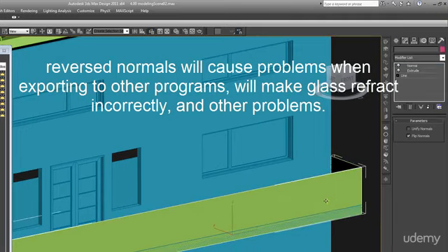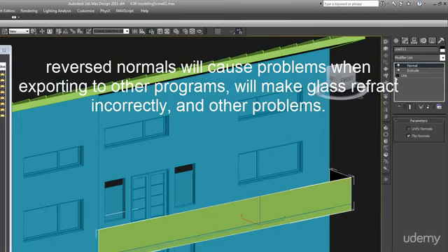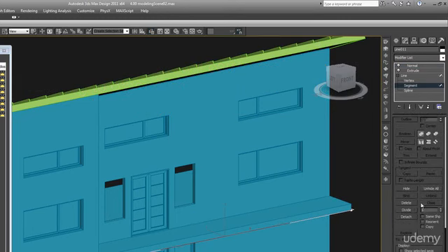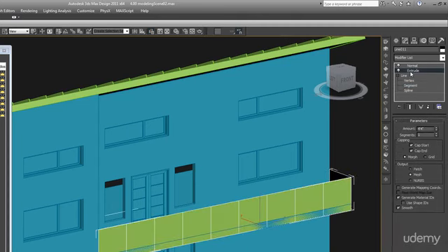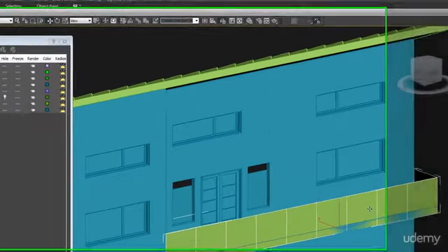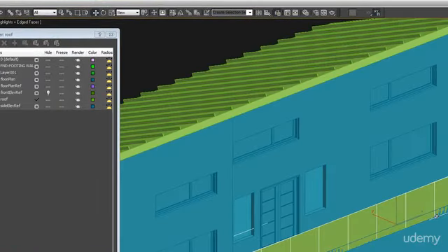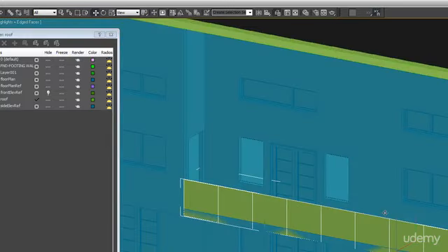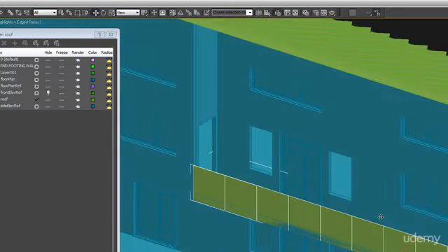So with this being an extruded line, what you could do is take this segment and divide it into here. If you go into the divide tool under the segment subobject level, you can divide that into, say, 8 pieces and then extrude it. You'll have that, and that's kind of useful. Not necessarily the way I do it. Well, this is one way to do it.